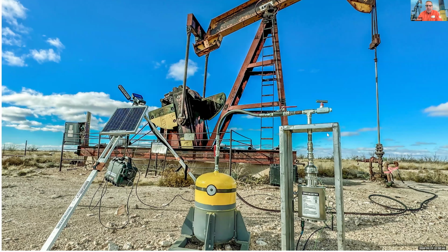I guarantee you that. This is a shot here of an Orphan well measuring in New Mexico, running the gas through a scrubber, which is actually, call it a methane minion, but it's to take any of the fluid or moisture out of the gas before it actually enters into the measurement meter there.